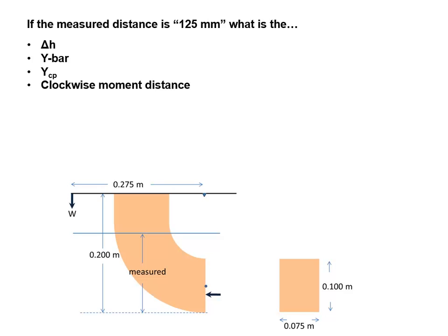And again, we're not able to measure that hydrostatic force directly. The way that we can measure what the hydrostatic force is by how much weight we had to add to put the balance back into equilibrium. So we can calculate the percent difference, once again, by just the theoretical value minus the actual value divided by the actual value times 100.